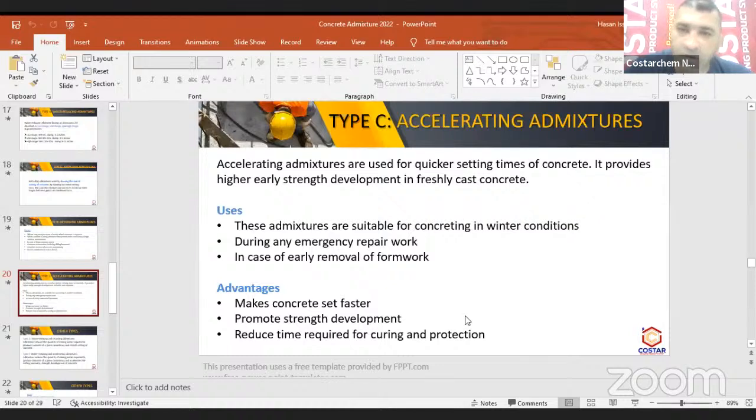And concrete will not become flat after 28 days. It won't. Actually, it will not even after a year. It will keep on progressing. You keep on gaining compressive strength. And if anybody disagrees, please call me. I have the tests for it. I have tested concrete for 2 years. I mean, cubes, I have made that.